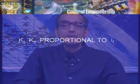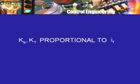If you apply a very large field current, then what is known as saturation can take place in the magnetic circuit, and therefore the flux will not be proportional to the field current. But if you do not reach that level, which normally one will not reach, then the torque constant and the EMF constant will be roughly proportional to the field current.